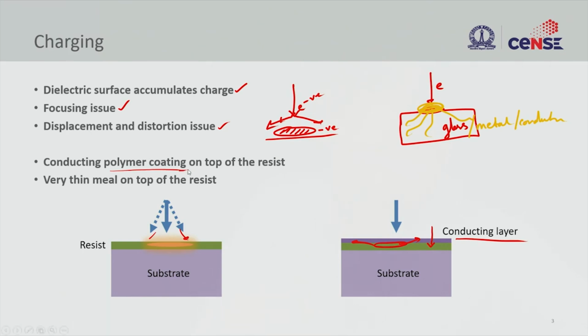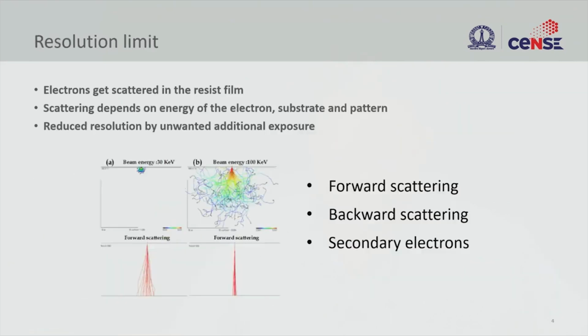So if you really have to address this charging issue, you can use this, but this strongly depends on the substrate. If you use a silicon substrate, you will not find this problem that much, but once you go to substrates like sapphire, or you have silicon dioxide as the top layer, it may be a silicon substrate but the top layer is silicon dioxide, you have this issue, or silicon nitride. So all these will have an issue of charging, while silicon itself may not have this issue.